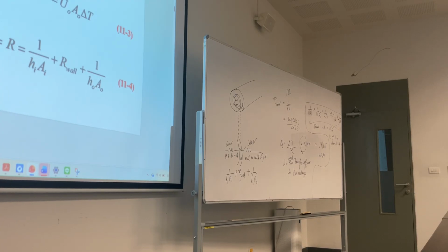Okay. It's a steady, not transient. If you remember from chapter 3, once we had calculated heat transfer rate inside or outside the window, it was same. Similarly, the product of UI, AI is going to be equal to U naught, A naught. Okay. U is called overall heat transfer coefficient. This equation 11.4 is very important. Okay, so you have to understand this.